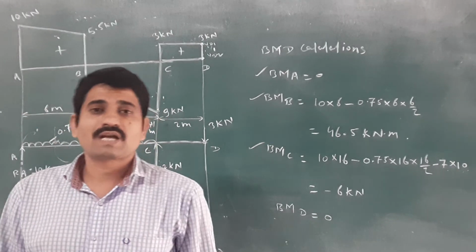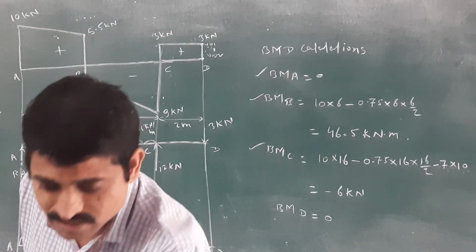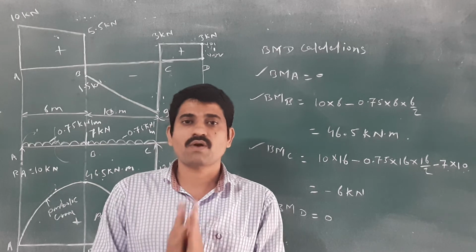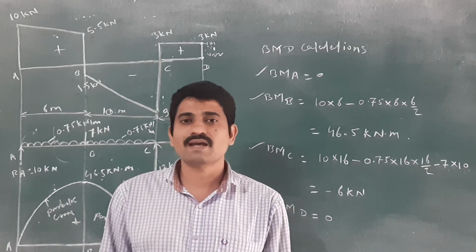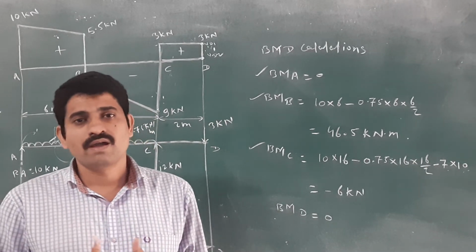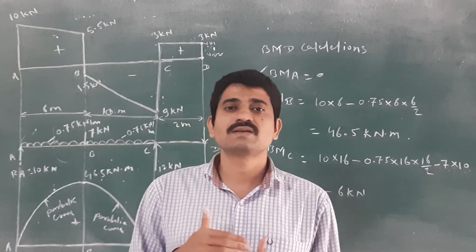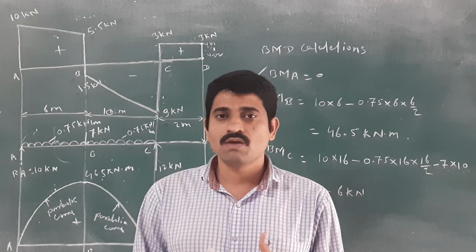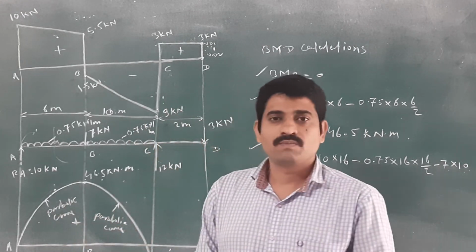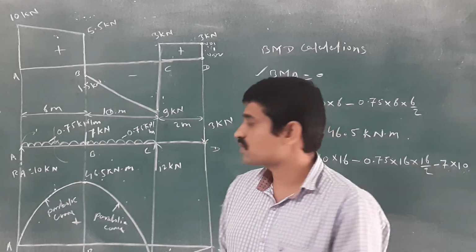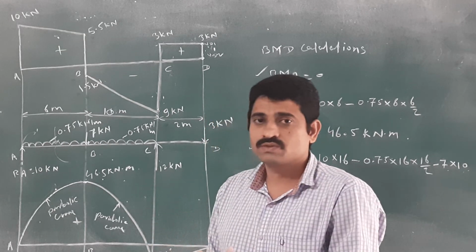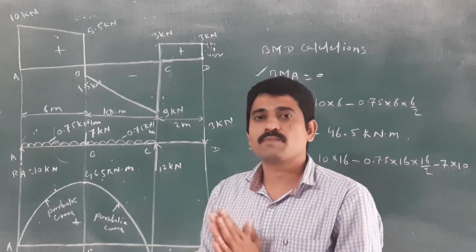Okay. Sometimes in exams you will get this type of question. You are given the SFD diagram. With the help of that SFD diagram, you have to draw the loading diagram as well as the BM diagram. Once you have got the loading diagram, then you can easily draw the BMD diagram. But how to do the calculations, you have to remember that.